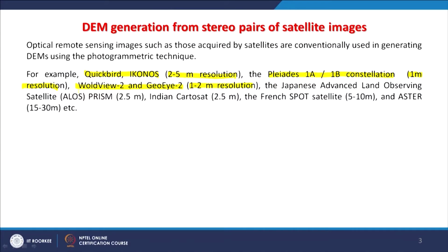Otherwise, one should try to resort to free data like ALOS data, Indian CARTOSAT data, or the French satellite data at 5 to 10 meter, or ASTER data which is 15 to 30 meter. In many cases we have found through our practical experience that even 30 meter spatial resolution digital elevation models are quite good. And if you go for 30 meter spatial resolution digital elevation models, then there are various options available to us,